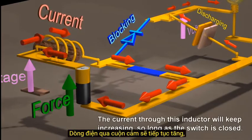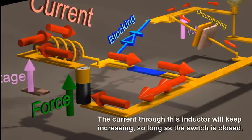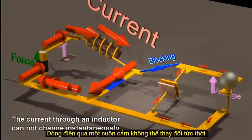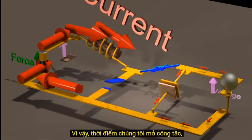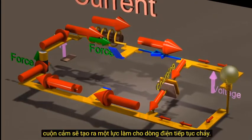The current through the inductor will keep increasing so long as the switch is closed. The current through an inductor cannot change instantaneously. Therefore, the moment we open the switch, the inductor will create a force causing the current to continue flowing.